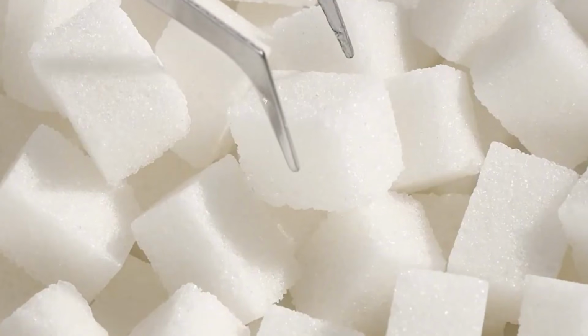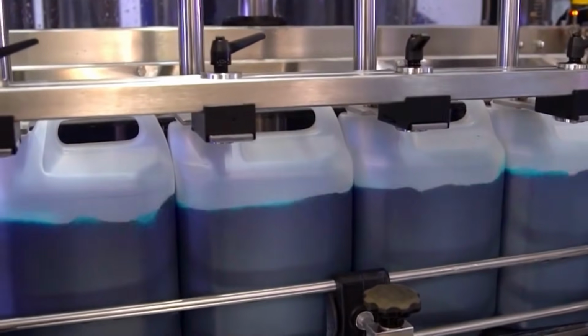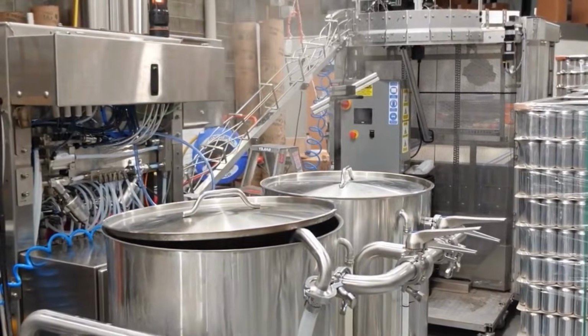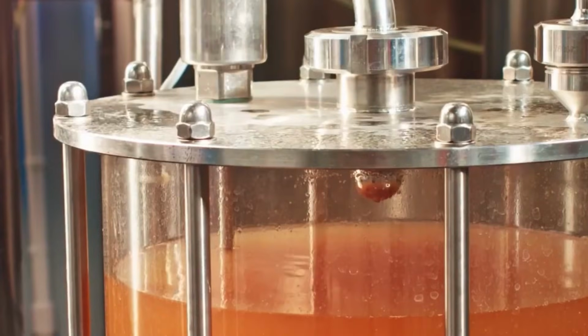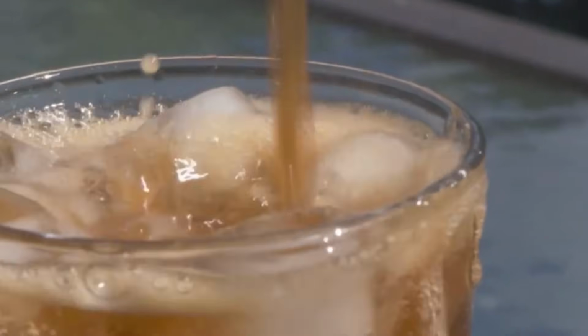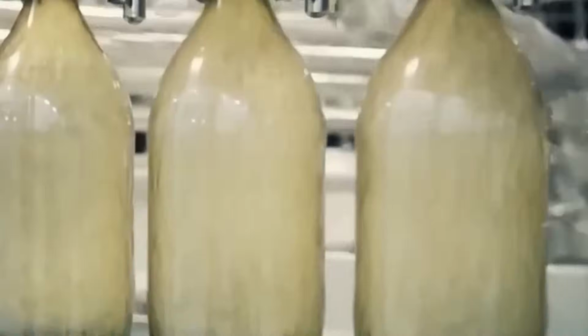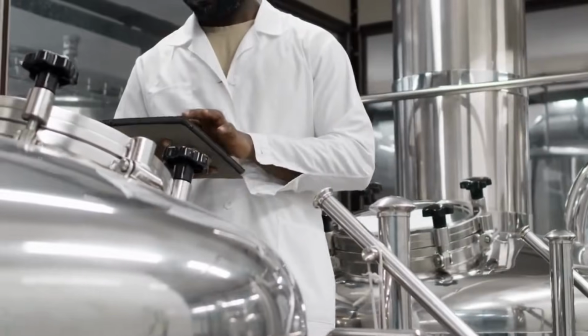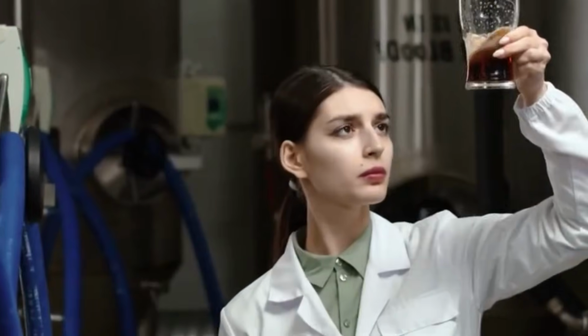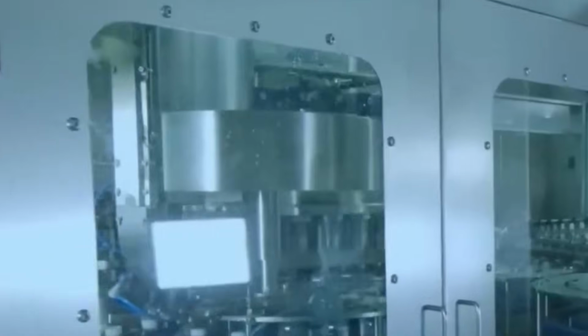Sealed containers pass through an inline quality control system. High-speed vision sensors inspect each container for correct fill height, cap application, label alignment, and structural integrity. Any defective item is ejected via air-jet nozzles. Simultaneously, select containers are diverted for destructive testing. These include pressure retention tests, carbonation level checks using digital pierce testers, and torque measurements for closure tightness. Approved containers proceed to labeling.